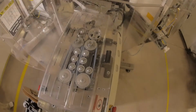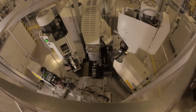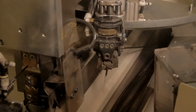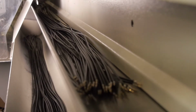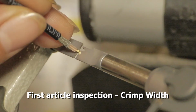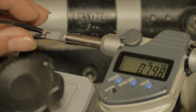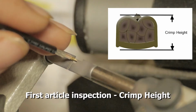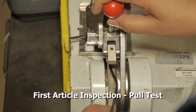Quality control checks are performed at regular intervals to ensure quality of the cutting and crimping process. The first article inspections are performed when the first few pieces from the production run are used for performing critical quality checks. Critical quality checks consist of measuring the crimp width, the crimp height, pull test to measure the retention force of the terminal to the cable.